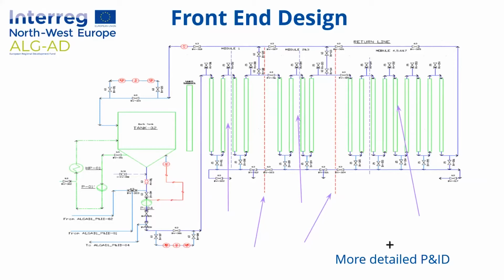And the idea being that when you first initiate or inoculate the reactor, you'd only use section 1, and you could return materials back to the tank from section 1 only, which means you don't need a massive inoculum in order to conduct the reaction. Once you've grown the algae in section 1, you can then open up section 2 and use what's in the system to inoculate section 2. And then similarly, once you've grown the algae up in section 2, you can then open up the whole reactor and grow throughout the whole thing.